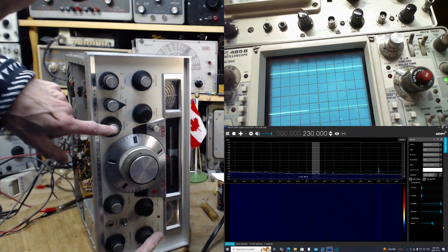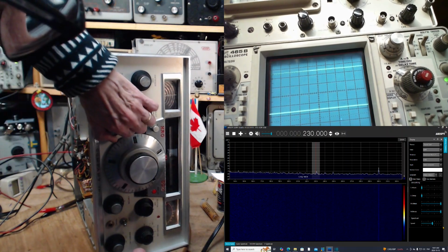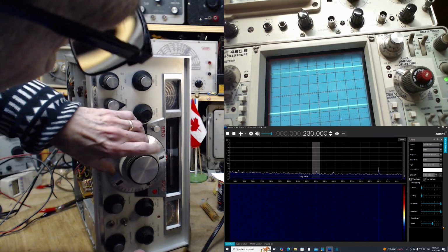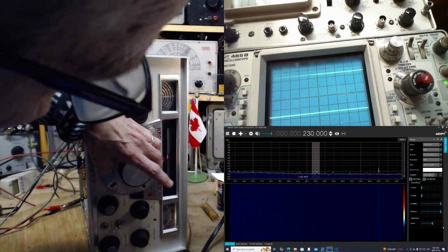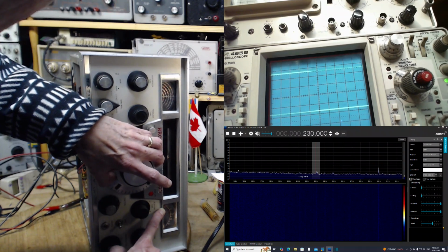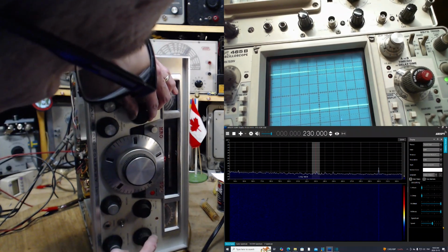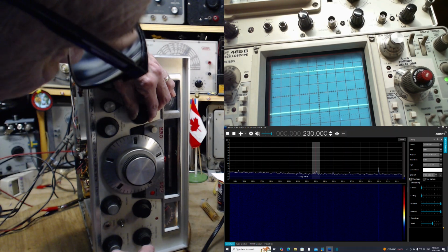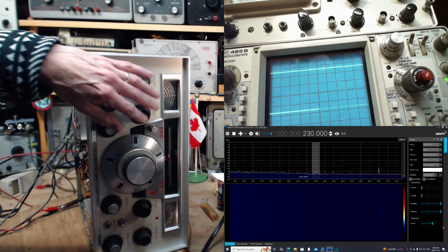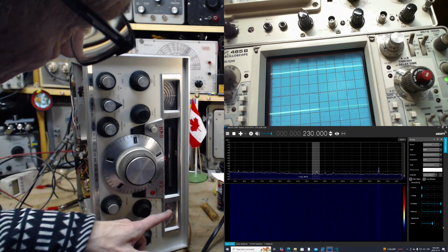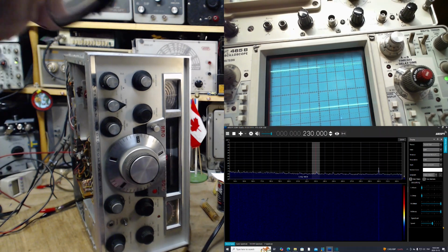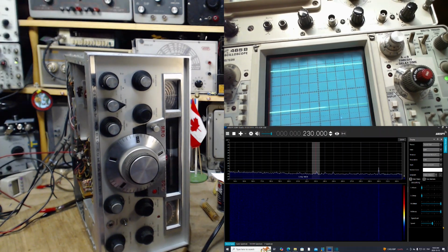So I found if you set the AGC threshold off, you don't have any AGC action, theoretically. And we should see it's just a little tiny bump. It's almost nothing. Okay, let's do this. Aha! This is so sharp. Trying to tune a sharp control on a fading signal, pretty challenging, but now we do have a signal, 9.33. This is a shortwave station that's almost always there.